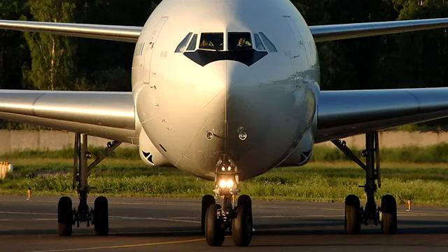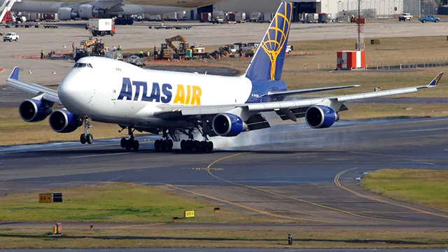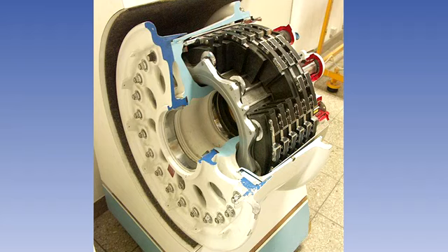The wheels and tyres of an aircraft support it when on the ground and provide it with a means of mobility for takeoff, landing and taxiing. The pneumatic tyres help to cushion the aircraft from shocks due to irregularities in the ground surface and take some of the shock on landing. The main wheels, and in a small number of cases the nose wheels, house brake units which control the movement of the aircraft on the ground and provide a means of deceleration on landing.